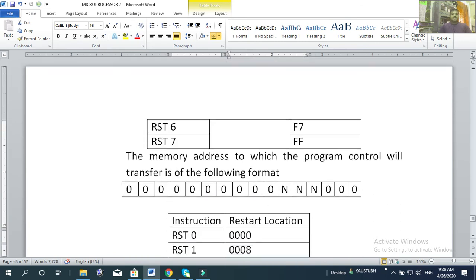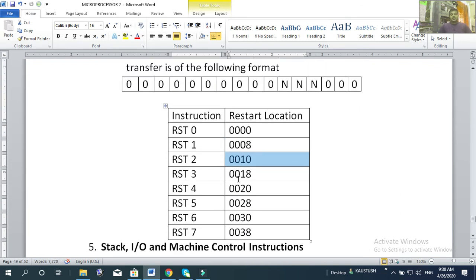So these are the branching instructions. These branching instructions are very much important. They are used when you need to take some decisions. As in high level programs we use if else, switch case, for loop, do loop, while loop, all those things in the 8085 microprocessor have to be maintained with only the branching instructions jump, call, and return. So jump conditional, unconditional, call conditional, unconditional, return conditional, unconditional.